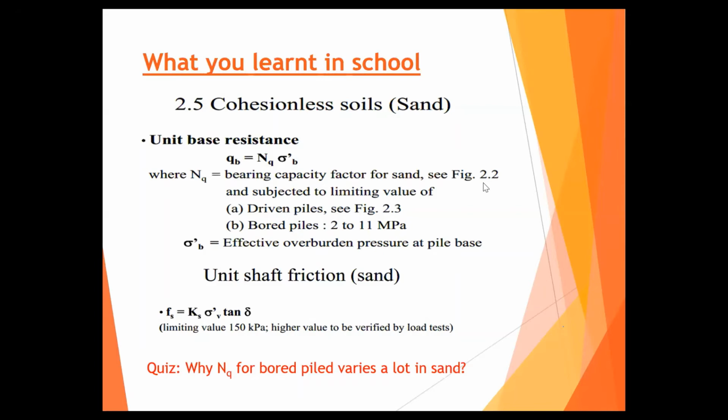Okay. Later you will know. Actually, in sand, we have a problem. Actually, bored piles a lot of the time depend on the workmanship. So why do they say it varies from 2 to 11? Because they take so many case studies. They notice how come some are very, very low, some very, very large.